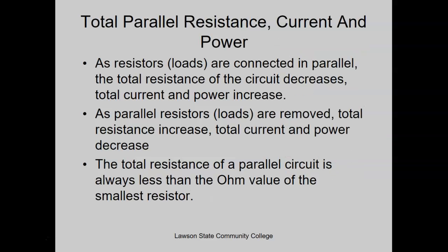All right, so total parallel resistance, current, and power. Basically, totals are the only thing that will change depending upon what you change in the circuit. Now, I'll explain that in a little bit, but we're going to go ahead and finish this. As resistors are connected in parallel, total resistance of the circuit decreases.